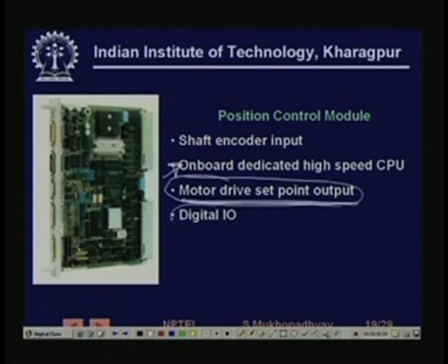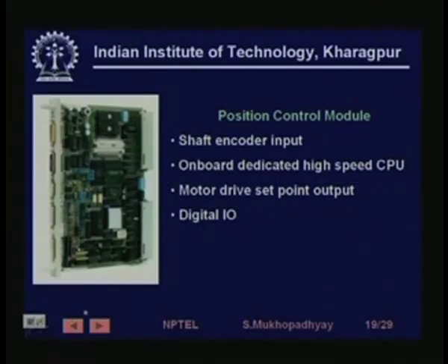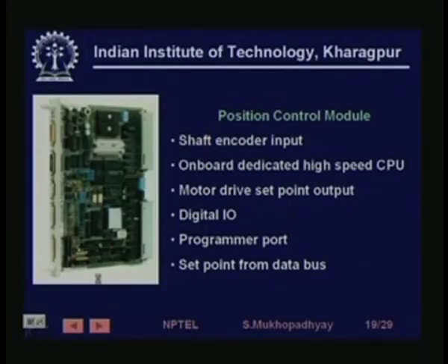It has digital I/O depending on what the final motor is; for example, a stepper motor is actually driven by digital I/O. So these are some of the modules used in PLC systems. It has a programmer port because there are a large number of parameters which have to be set, and the set point comes from the data bus.